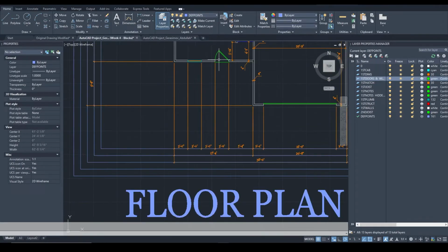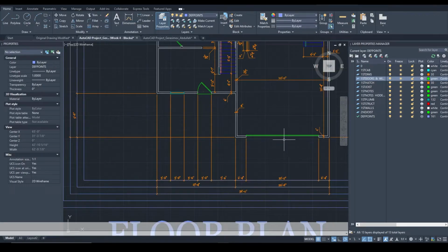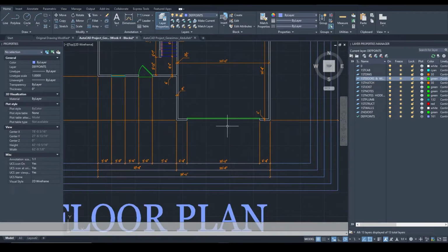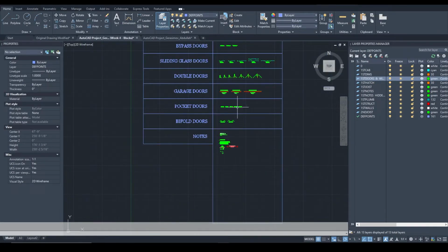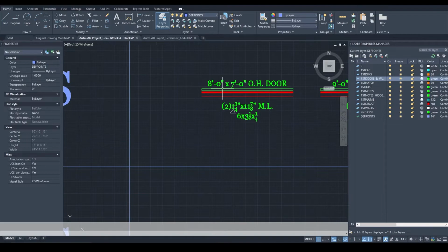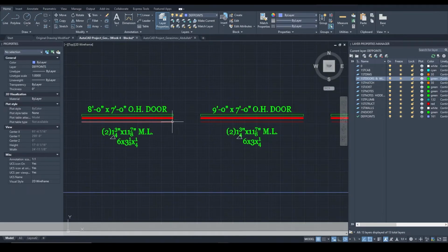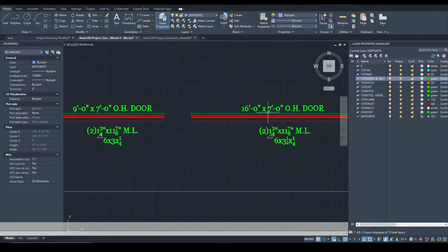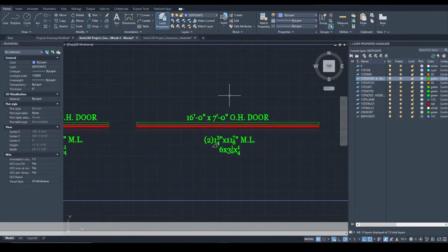Once you create this door, which is again a 3-foot offset from this window, let's move on to the garage doors. Typically, garage doors on residential houses come in 2 sizes: 8-foot doors for single cars and 16-foot doors for double cars. You already have a block ready for you to use. At the garage door there are more lines associated with them, which right now we're not going to touch because they represent structure. We're going to go with a 16-foot by 7-foot door. 7 feet is the height of the door. It's not the most typical. There are 8-foot doors, there are 6-foot 10 doors, and others.